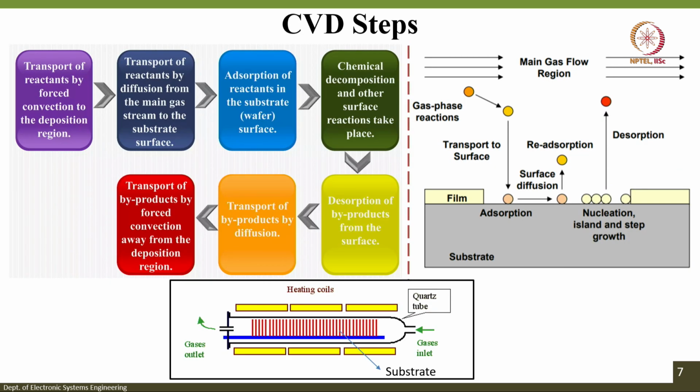The figure shows the basic steps of a chemical vapor deposition process. This is the first step. As I mentioned, you will have a chamber. For example, in the figure below you can see there is a chamber where you will have a substrate holder, and you can arrange your substrates in the manner required, and you will have an inlet where the precursor molecules are taken to the inside of the reactor, and chemical reactions take place in your chamber, and a layer of film will be deposited or formed on your wafer surface.